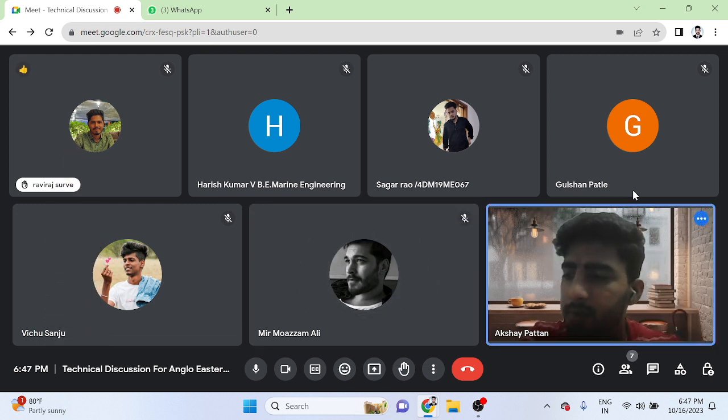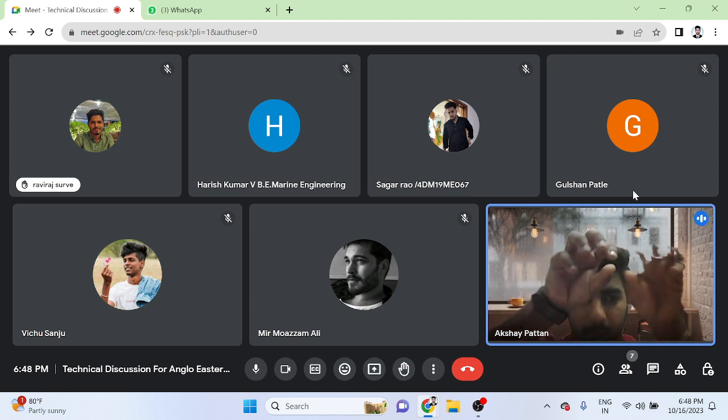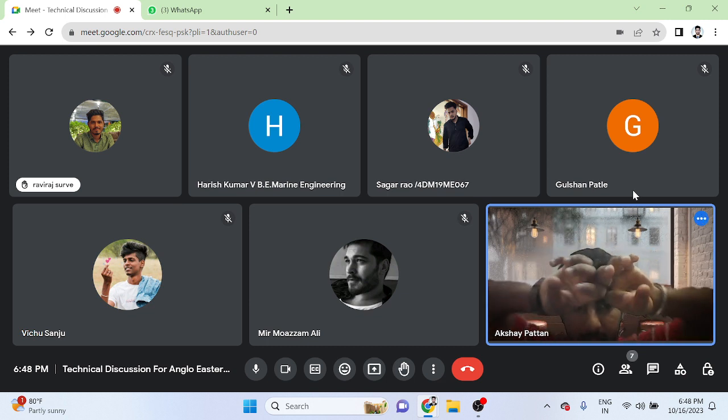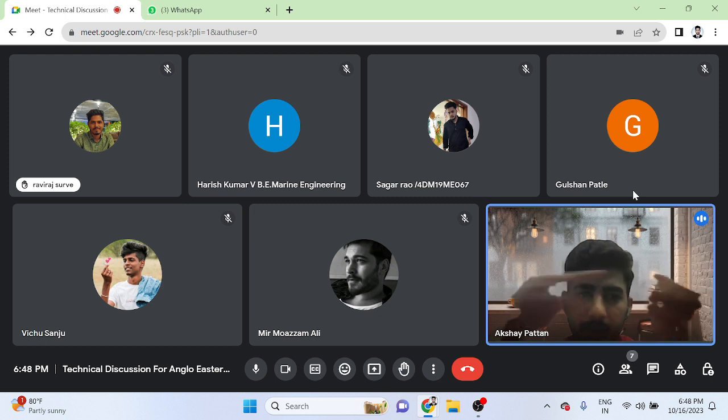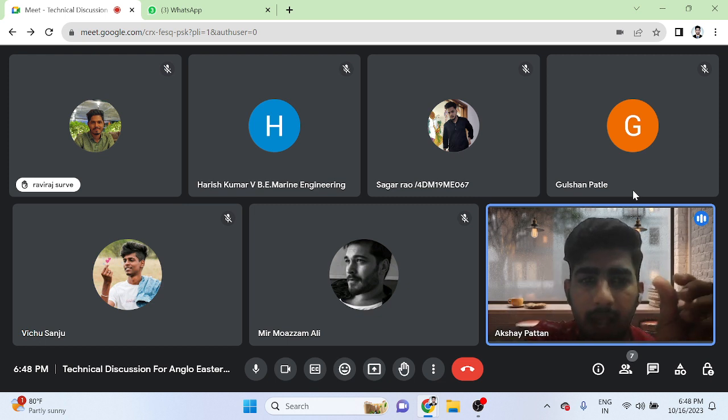When we look at the diagram, there are two gears. One is a driver gear and another is a driven gear. Both the gears are meshed. The driver gear is the main gear which rotates, and due to meshing, the other gear, the follower gear or driven gear, also rotates. Both the gears rotate in opposite directions. When the gears unmesh, in the sense when both gears are joined and then unmesh, the volume in the casing increases. The line where the gears unmesh is known as the suction line.